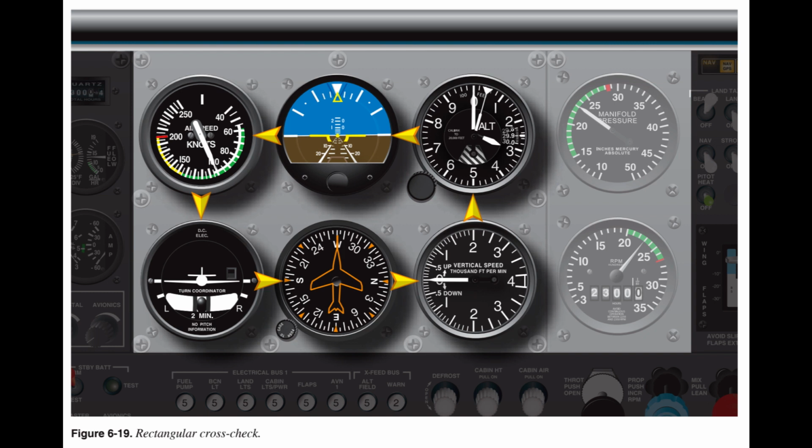While fixated on the instrument, increasing tension may be unconsciously exerted on the controls, which leads to an unnoticed heading change that leads to more errors. Another common fixation is likely when initiating an attitude change. For example, a shallow bank is established for a 90 degrees turn and, instead of maintaining a crosscheck of other pertinent instruments, the pilot stares at the heading indicator throughout the turn.